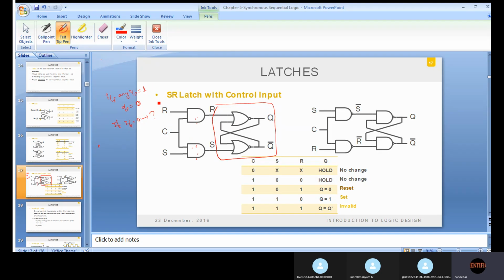So I am giving R, look here. In the first case it will be hold state only, no change. So I have given C is equal to 0. You give R as 1 or 0, and S as 1 or 0. If one input is equal to 0, what will R and S be here? It will be 0. When both are zeros, what will happen to the flip-flop? It will be in the previous state only.